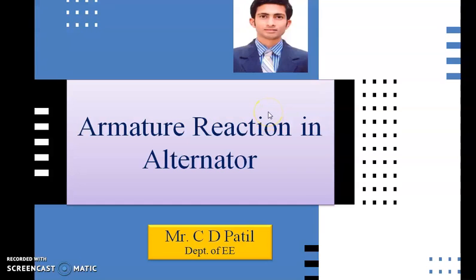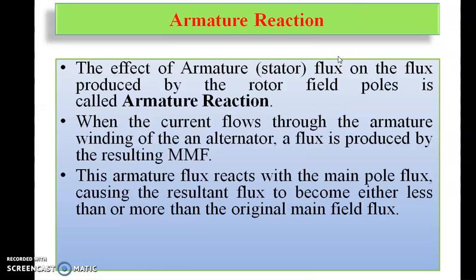Hello everyone. For this lecture, we will see about armature reaction in the alternator. Now, this armature reaction, we will see about definition first. The effect of armature flux, that is the stator flux, on the flux produced by the rotor field pole is called armature reaction.